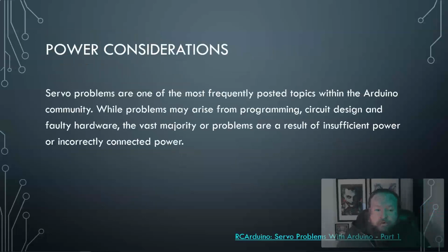And as we're reaching the end of these notes, coming soon is, again, worrying about the power considerations. I've said this multiple times, that a lot of the problems that come with projects, if you look on other forums, you'll see that there are issues that come from power, like power due to servos, and that was the real issue they were having. So it could be from programming and how you've set it up. So those weird pins, like, oh, I didn't put my servos on 9 and 10 and I tried to put a light and it's not working, or something else that required PWM and I have analog writes and it's not doing anything, because it will still compile, but won't work when it runs on the actual device.